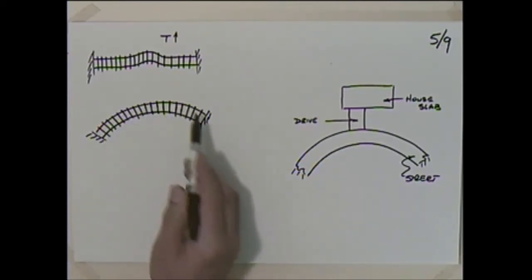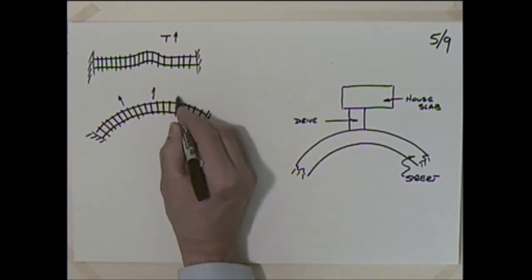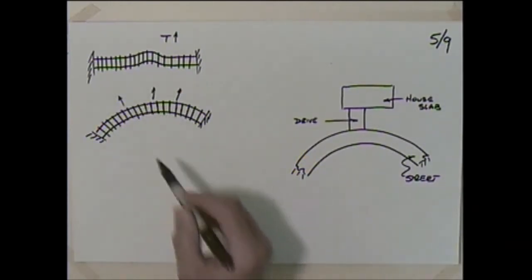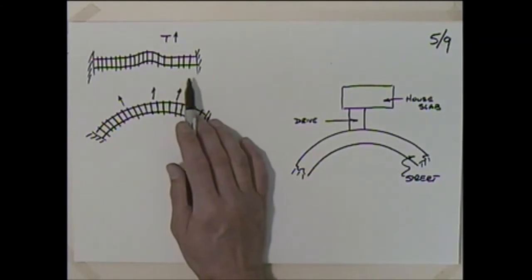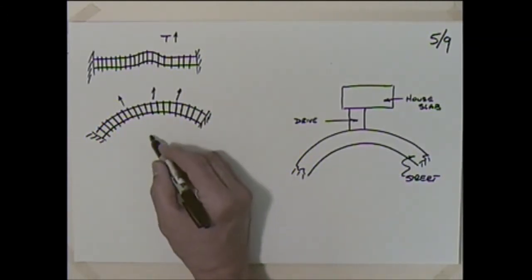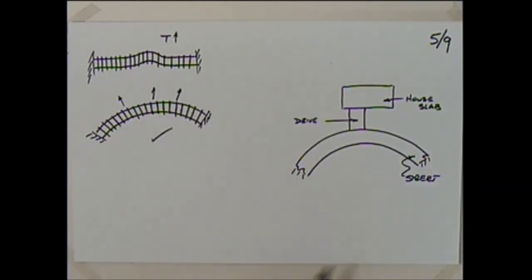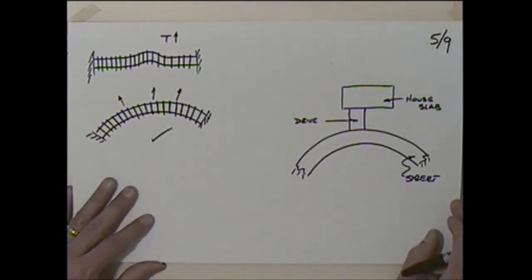Usually, there's natural things that help with this, and that's just curves in the track. You have a general curve in the track, and if the temperature increases, the track is just going to push out slightly in the gravel bed, and usually that is not a problem. This also happens with steam pipes, very long steam pipes. They'll have to put a bit of a curve into it, an expansion joint or something like this. Well, this phenomenon of a curve just expanding harmlessly on the track, I saw an interesting example one time where this didn't happen so harmlessly in terms of a street.